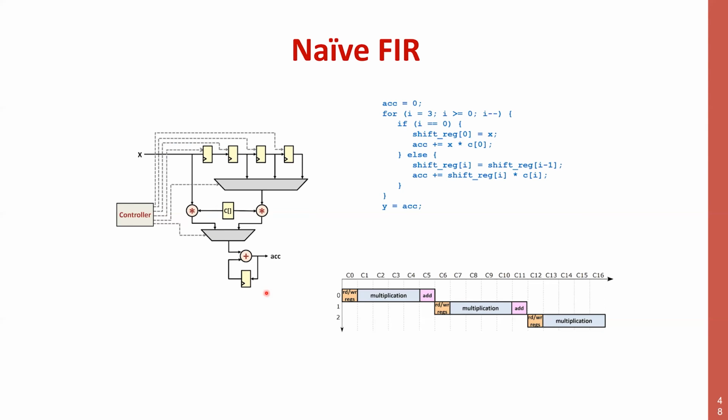And this circuit, if you give it to Vivado HLS, by the way, all these results I think are literally true. If you put the code that is here in Vivado HLS, you get one of these execution schemes, or timing diagrams, that you see below. And of course, we are not happy because it is completely sequential. There is no difference between this and taking a processor, the worst processor that you have, and doing this. I hope you start seeing what is happening, right?